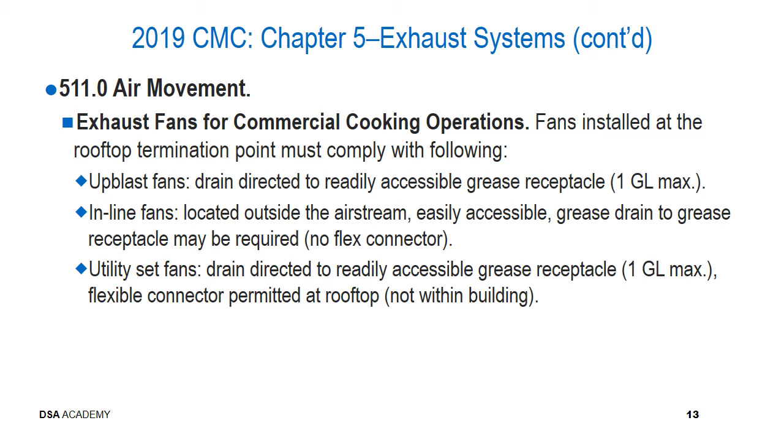For any utility set fan, there are basic requirements, and that is they must drain directly to a readily accessible grease receptacle, again, that is 1 gallon max in size, and a flexible connector is permitted at the rooftop, but again, a flexible connector is never permitted within the building.